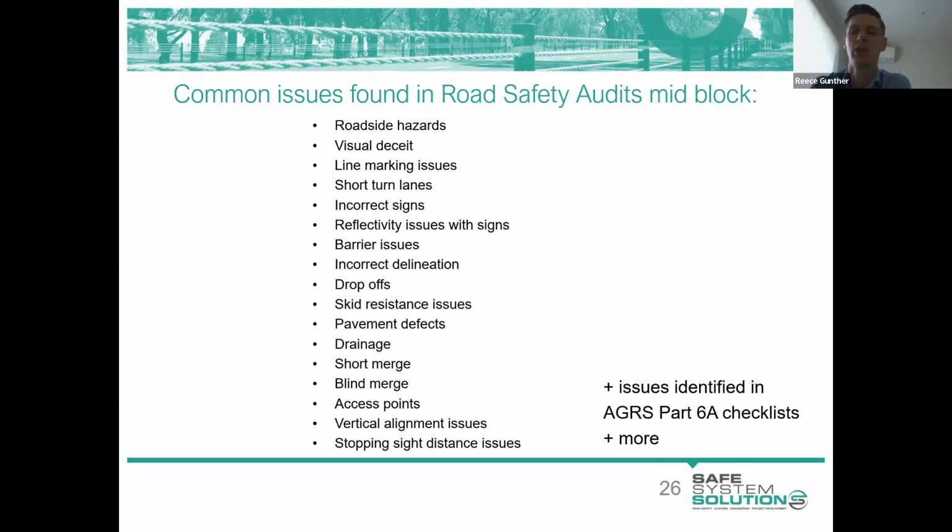If you're a traffic engineer, try and pair with a road designer, or with someone with construction knowledge, because you're going to pick up more things in your audit. People become focused on what their expertise or skill set is. So your audit's going to find a lot more issues, and you'll be able to remove them or provide treatments that lower that risk.